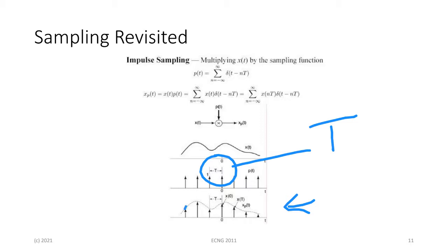you can see approximately that the sample points behave a little bit like what the real signal looks like. If you were to decrease T, in other words, T gets smaller, so we were sampling here, here, here, here, here, in between here, you get these additional values, and you start to get closer and closer to what the real signal looks like. So there's a relationship between how good the sampled signal is and the real signal, and that relationship has to do with T.